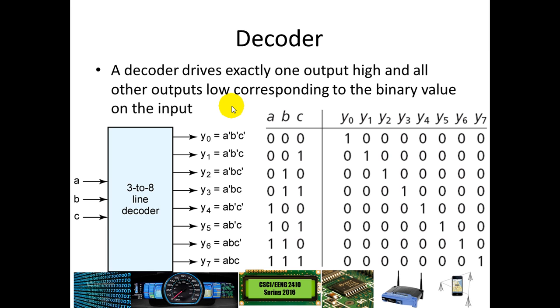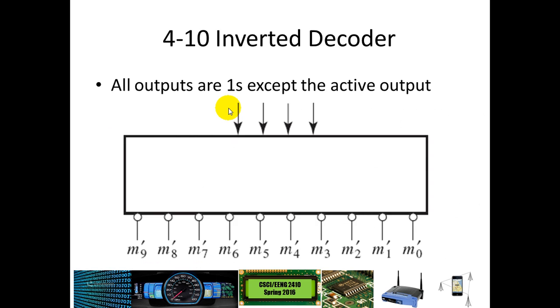That was actually part of a project that I did when I was an undergraduate in our microprocessors class at Virginia Tech. We actually had to wire up our own external ROM chip, and in that case we needed extra addressing capabilities, so we sent some address bits to inputs on a decoder, and then the outputs determined whether they were selecting internal memory or external memory that we wired up.